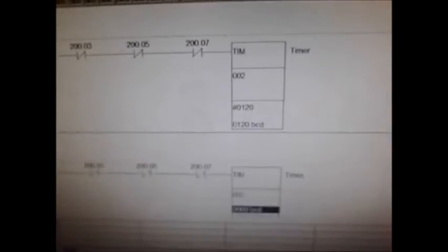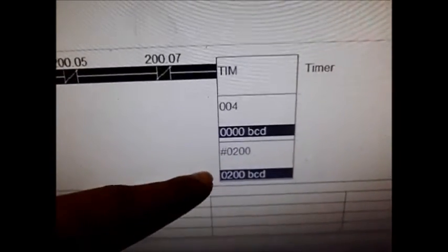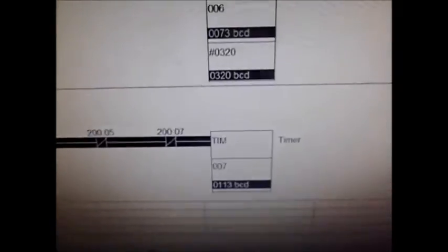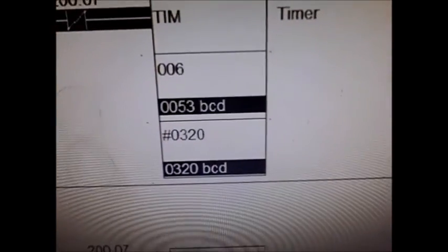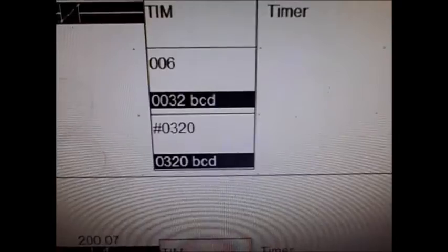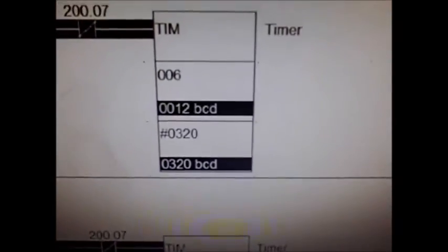As you can see, for the timers, it starts from its initial value, goes down to 0. Each timer is allocated for each different lane. As you can see in network 3 and network 4, a timer is counting down at the moment because the lanes are changing. And you can see in network 6, the timer is counting down, it will go to 0, then it will go on to the next timer.